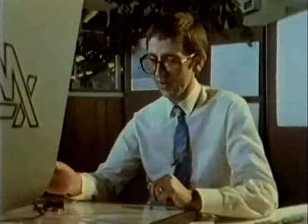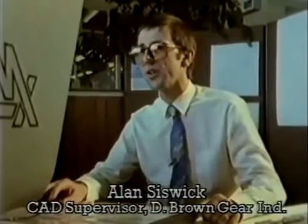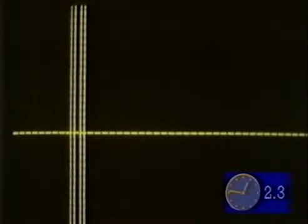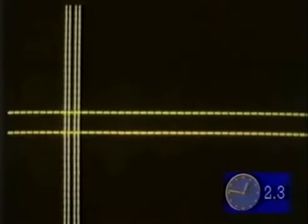CAD supervisor Alan Siswick: All right, well, we'll start off doing this cover drawing in terms of using the system. First of all, we'll set off some construction lines for reference, put on a vertical and a horizontal. We can then take some offset lines from there to give us the width. Having put the offset lines in that way, we can come back and put some more horizontal ones in. The offset construction lines will be used to build up the outline of the cover's profile.